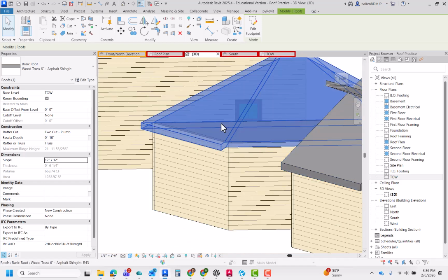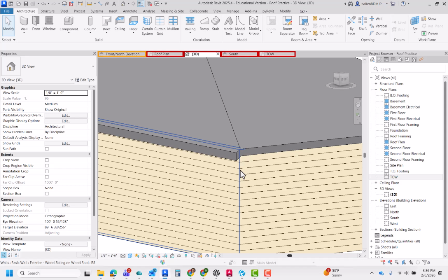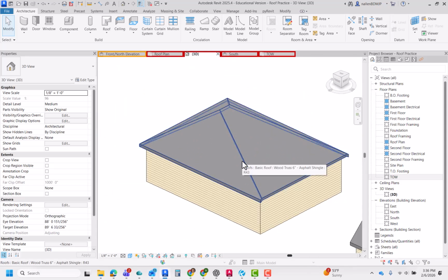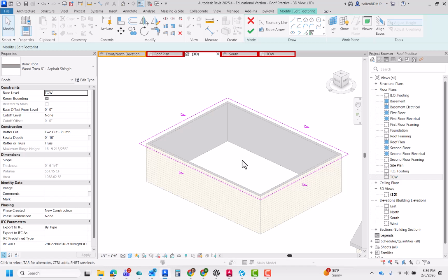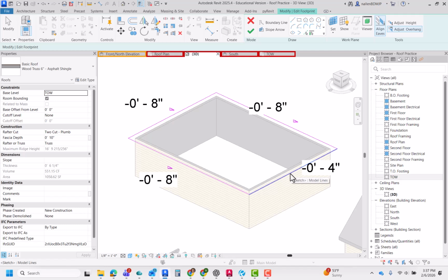Okay, we have a problem. 2 different slopes means 2 different fascias. And that's always something we're going to try to avoid. There's a really cool tool that will fix this. I'm just going to go inside, back to the edit mode by double clicking, and I'll use the Align Eaves tool. And this tells me that all of these eaves are 8 inches below the edge of my wall, whereas this one is 4 inches. And by using this tool, if you look down here, it says select an eave to align to, and then select eaves to be aligned.